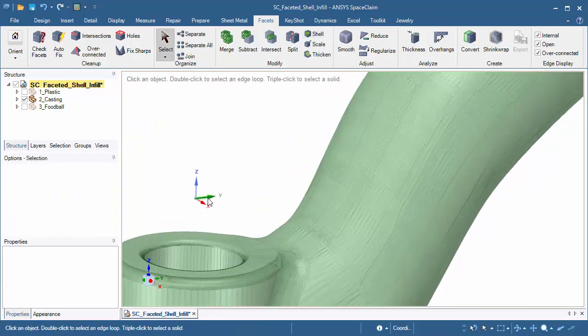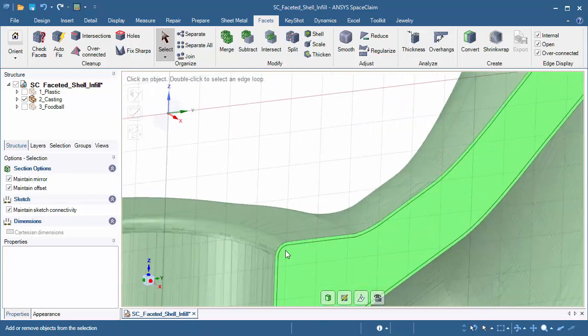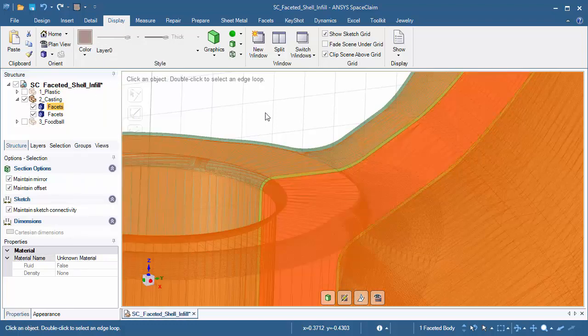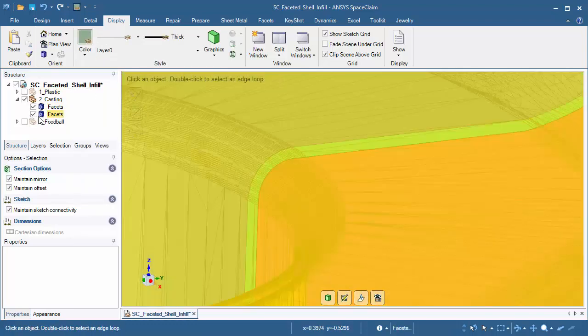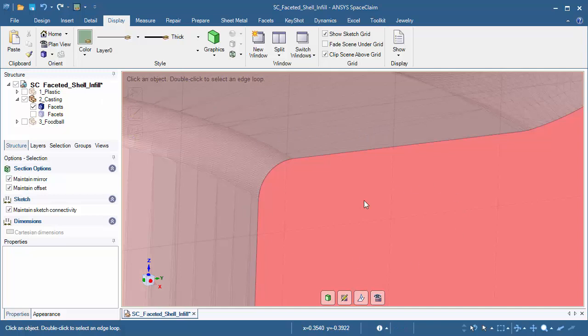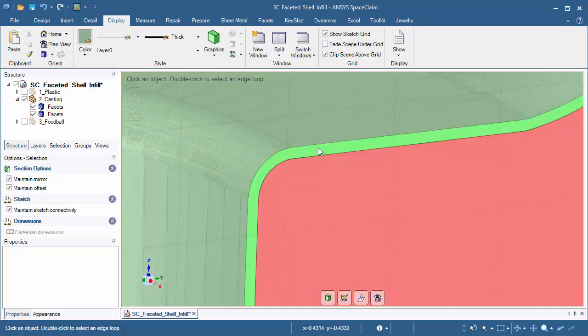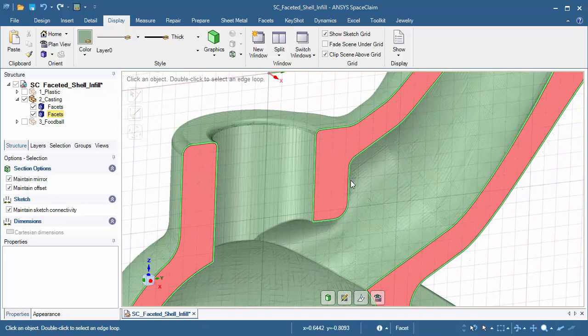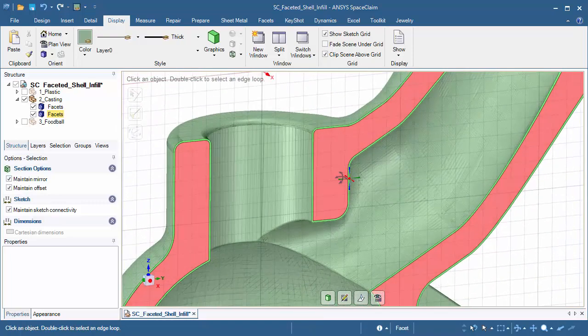I'm going to escape out, and I'm going to select Y and Z and go into a cross section. And actually, I'm going to select one of these, and I'm going to change the color. So what we actually have here is the original inner body, and added onto it is like a layer, a film, a skin, but with a thickness. What it did was it took the outside face of the inside body, in essence, copied and pasted it. It reused it. And then it offset it outward, and it made a body out of that. So, there's a lot of applications for this. If you literally need to make a skin or a film for something, this will do it right here.